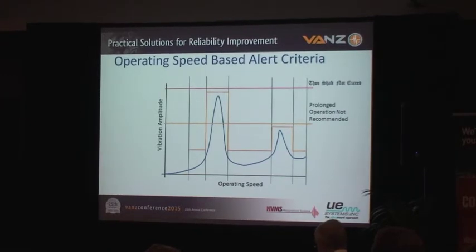And this is what I refer to when I talk about compartmentalizing the data, focusing the data on the specific operating state and doing your statistical alarming based on what's normal for this machine at this speed, at this load, operating under these very specific circumstances.